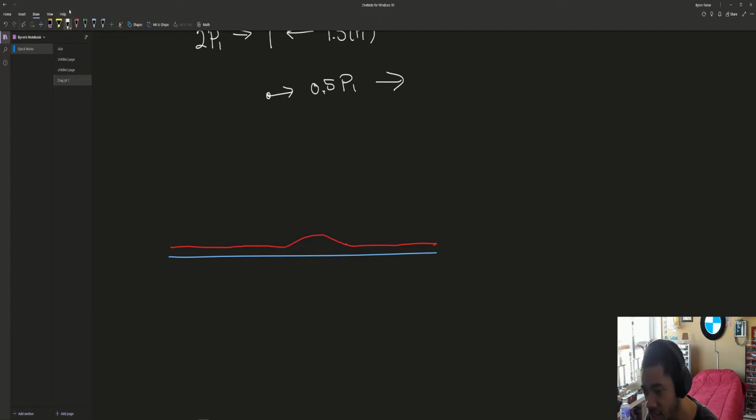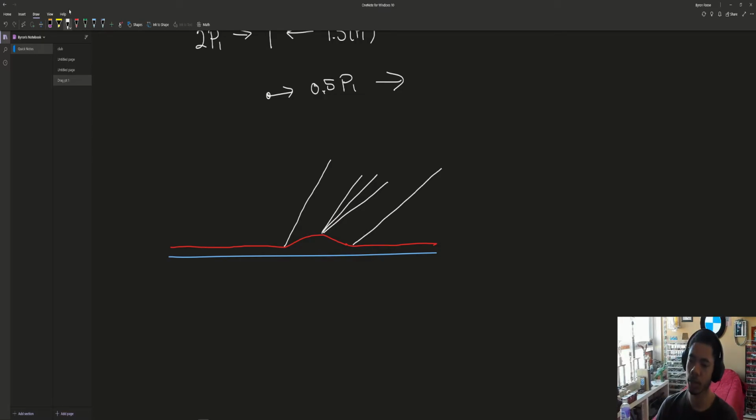What happens is that if this is the case, due to this boundary layer, you're going to get an oblique shockwave that occurs right here. But because it starts to go back down, we're going to get this expansion fan that happens along the way from here. And then as the flow goes back in, we're going to get an oblique shock again.